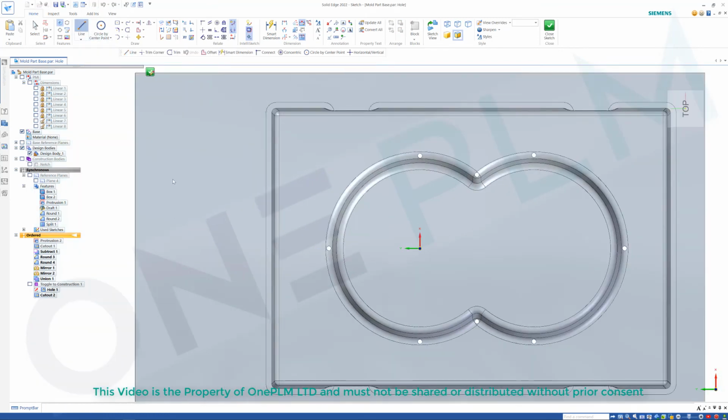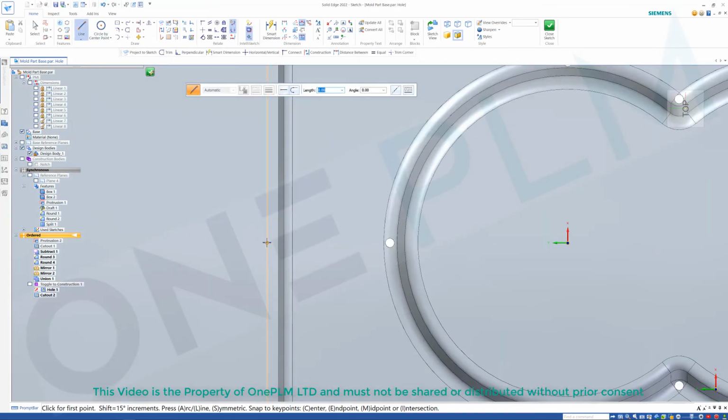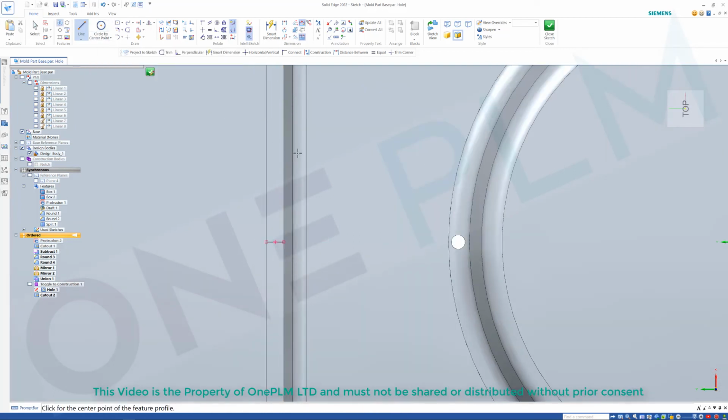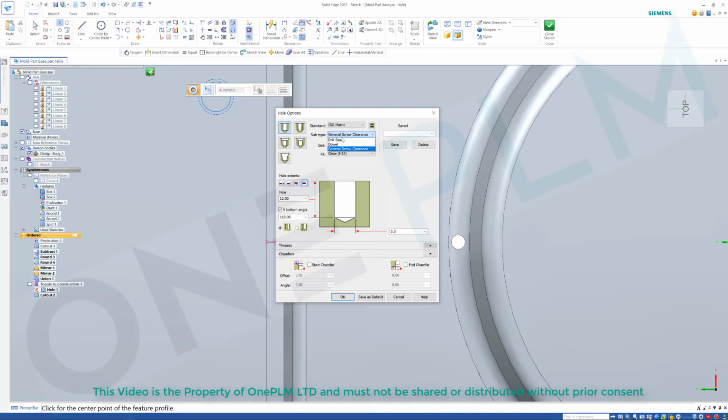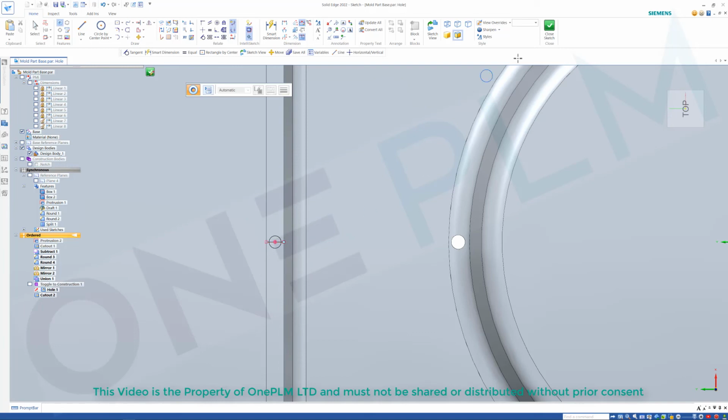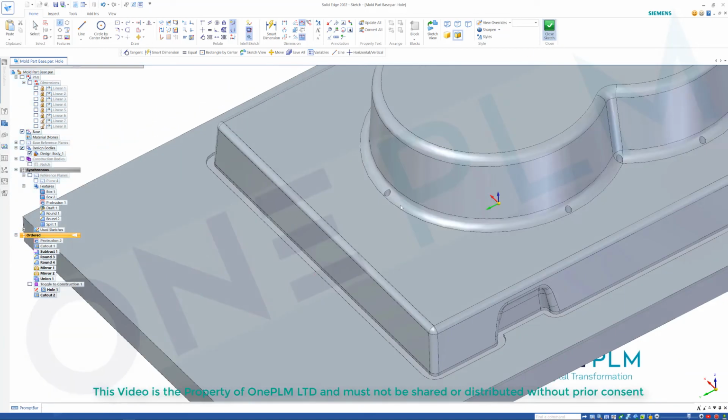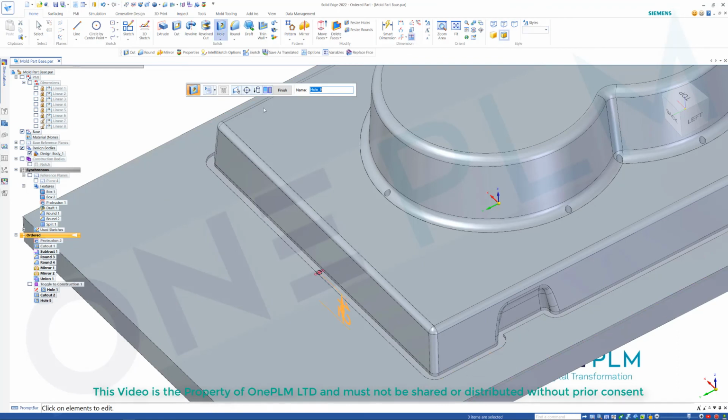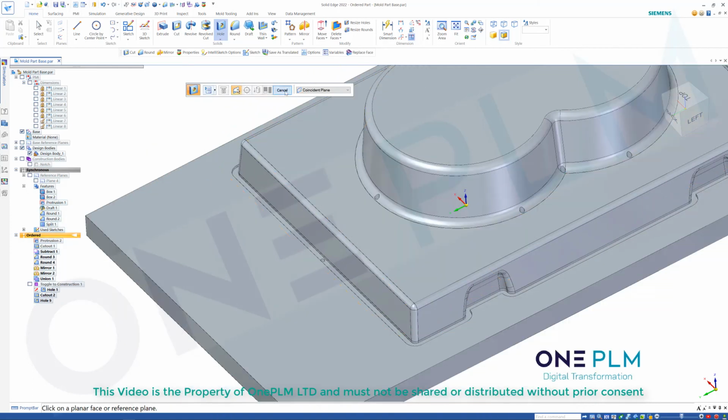Again, what I said earlier about placing that hole: because I'm just doing the one, I'm going to make sure that even if we change the hole size, it's going to snap to the center of that line. So if I now go into the hole, let's do the same again and turn that into a standard drill size. I'm going to go slightly smaller this time, 1.75. Click OK. Snap to there, close our sketch. Then make sure that our extent step is through all or through next, and we'll go down and finish that hole on there.